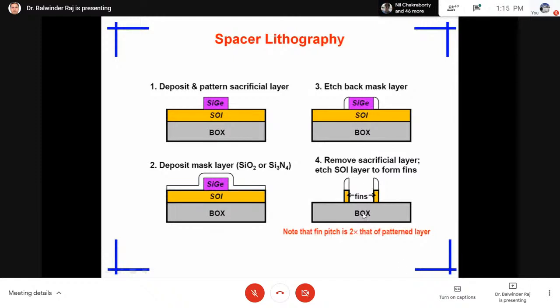You can see the barrier oxide with the fins. Here two fins are shown just to show how we can move step by step to form this. Similarly, multiple fins, 3 fins, 5 fins, 7 fins, can be designed. The higher the number of fins, the higher the driving capability. But you can see here that multiple fins require more steps. The fabrication will be a little bit complex.